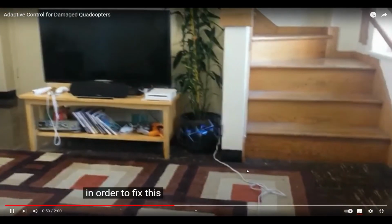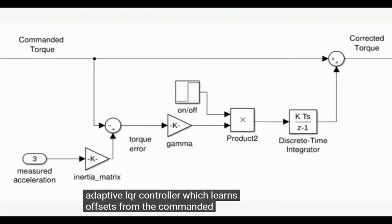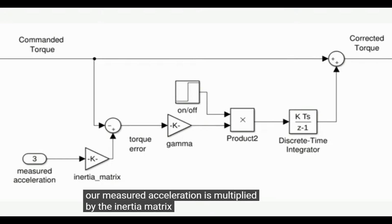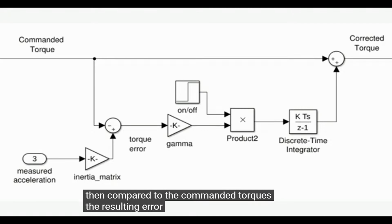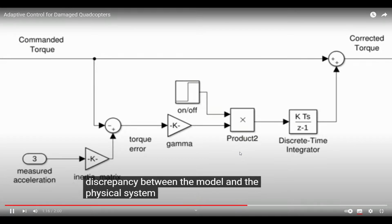In order to fix this, we design an adaptive LQR controller, which learns offsets from the commanded thrust and torque to make our expected acceleration match our measured acceleration. Our measured acceleration is multiplied by the inertia matrix of the drone and then compared to the commanded torques. The resulting error is then multiplied by learning rate gamma and integrated. Discrepancy between the model and the physical system generates these torque offsets, which are used to correct the output of our model system.